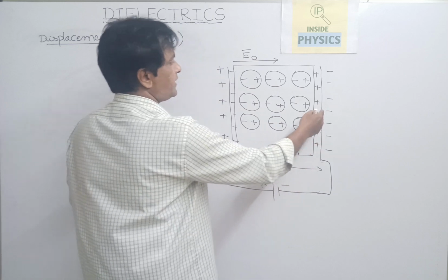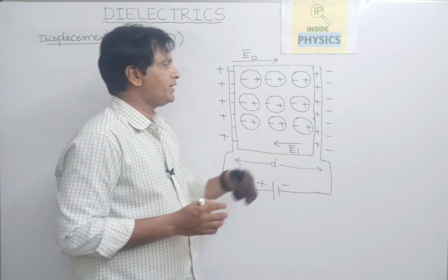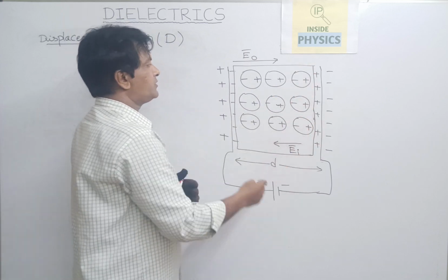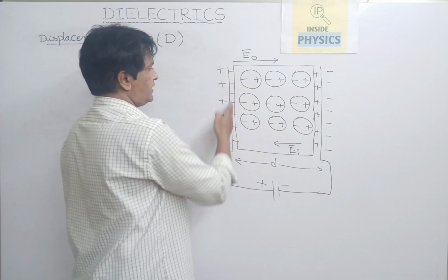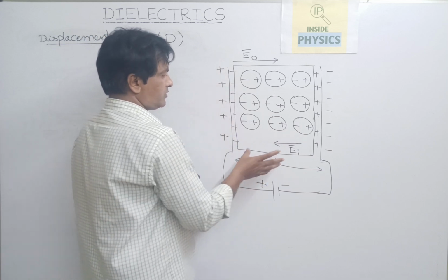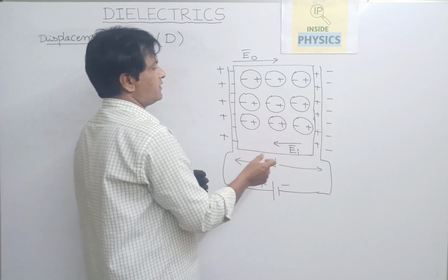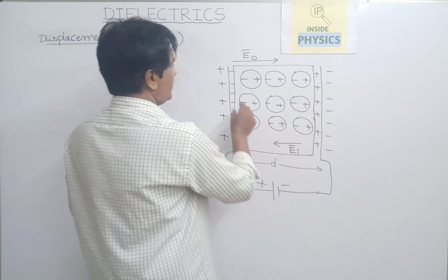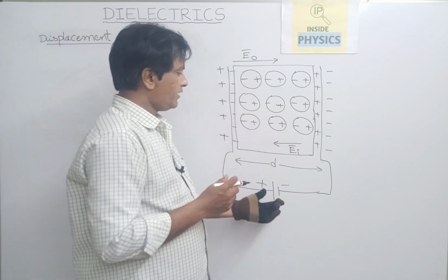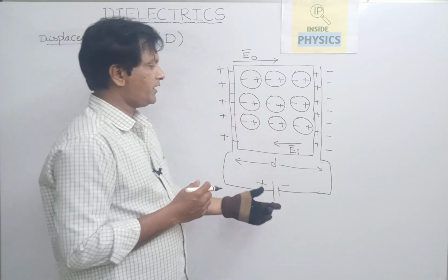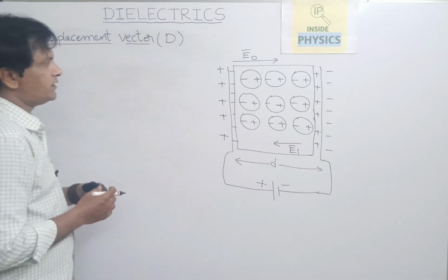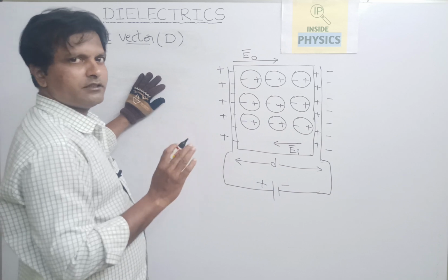So this negative charge will accumulate on this plate, and without dielectric we can imagine the accumulated negative charge will be attracting the positive charges onto this plate. So because of this Coulombic attraction, the charges are held on this plate, and the capacitor will store the charge while the DC power supply is supplied, and the stored charge is nothing but the displaced charge.